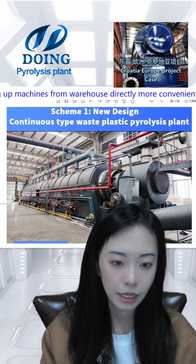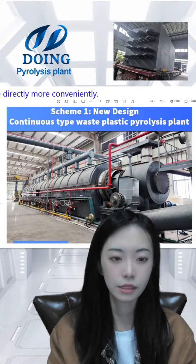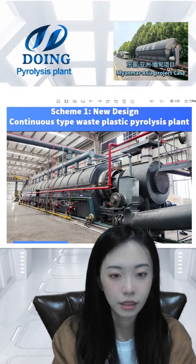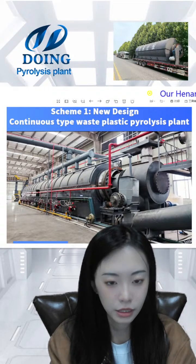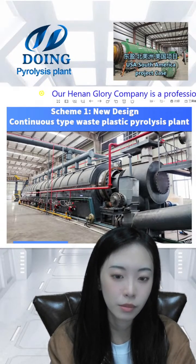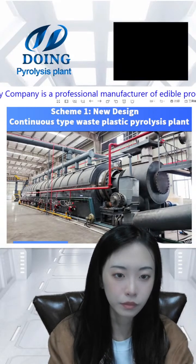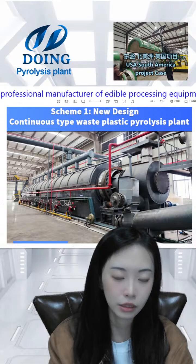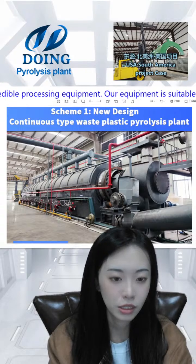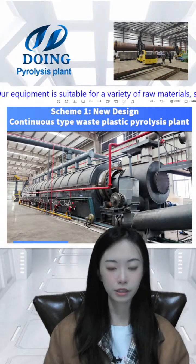And for some other waste, like paper mill waste or daily waste, it depends on how much water and how many other materials it contains. If you get pure paper mill waste with no water inside, meaning dry materials, then the oil yield can reach 60%. But if you get wet materials, then the oil yield is nearly 20%. So the oil yield is different and depends on the type.